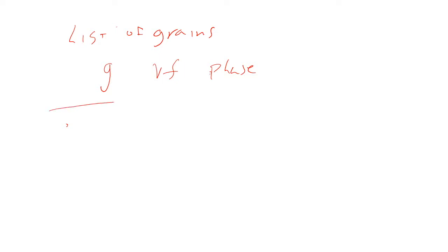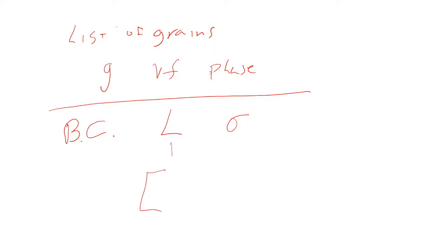Okay. So then we have to apply our boundary conditions, right? And these can be mixed. You give it components of the velocity gradient tensor, and you give it components of your stress, right? So in this case, say we're doing compression. So first off, I say don't allow any shear.